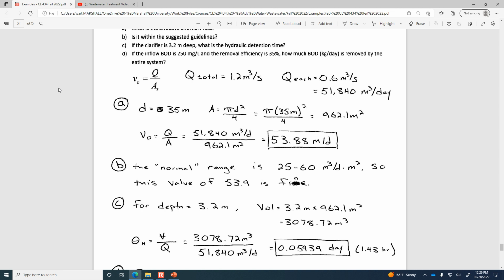You know, just sometimes for visual inspection you can get a sense of the scale of things. You know, the rate that water's coming into a tank, the relative size of the tank. If this had said that it was going to be in the tank for 55 days, then, you know, maybe we'd scratch our heads and wonder if we'd made a calculation error along the way. Or if it said it was going to be in the tank for 55 seconds, you know, that's visually not obviously true. When we looked at the video, for example, of a clarifier, how slowly the water's entering, how little goes out in each time increment.